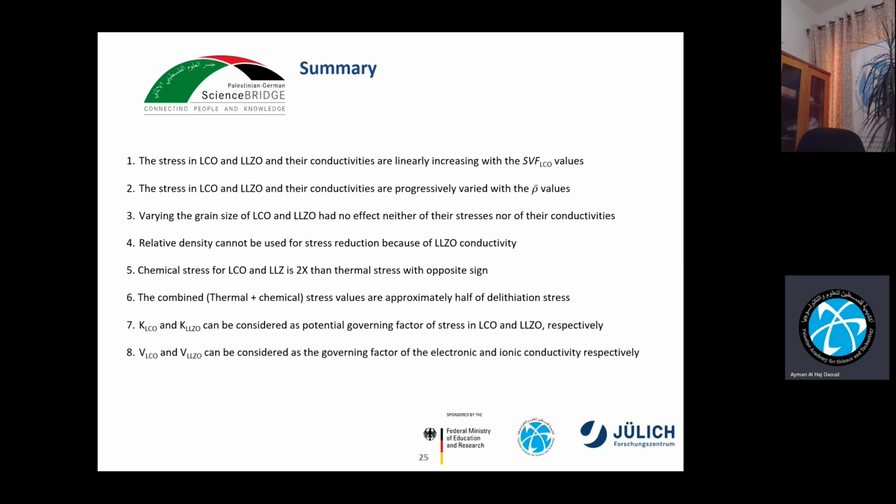This is very important. So, the summary of my talk: the stress in LCO and LLZO and their conductivities increase linearly with the solid volume fraction of LCO. The stress in LCO and LLZO and their conductivities progressively vary with the relative density values. Varying the grain size of LCO and LLZO had no effect on either their stresses or their conductivities. Relative density cannot be used as a stress reduction method because of the LLZO conductivity. Chemical stresses of LCO and LLZO are 2 times higher than the thermal stress, with the opposite sign. The combined thermal plus chemical stress values are approximately half of the delamination stress.